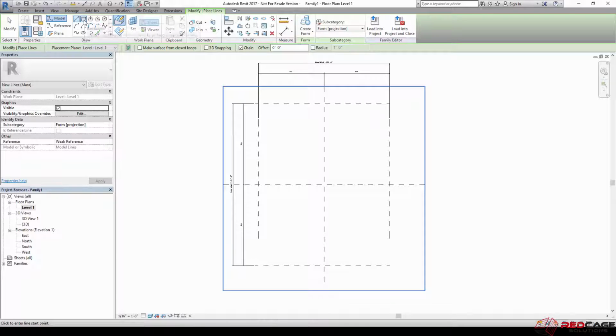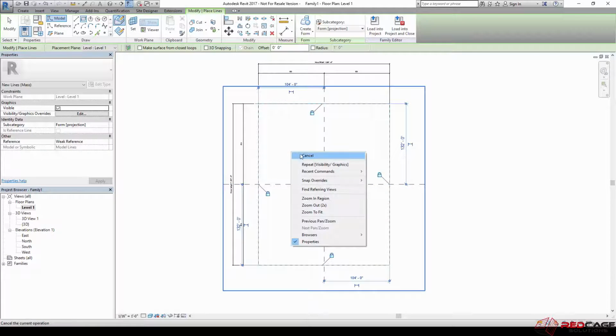So I'm just going to click on the rectangle tool here so I can get these all done at once. And I'm going to go to where these planes intersect. Okay, so I can see that it snaps to that one, and then I'm going to come down to this one. And by using a rectangle tool and drawing that in, I get all 4 lock constraints at once. So now I can click these 1, 2, 3, 4. And essentially, I have enough now to create this mass.